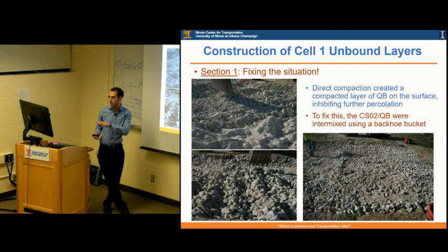Like a weak layer in between the two layers that is causing more permanent deformation, because permanent deformation is closely related to shear properties of unbound materials. So you don't have maybe the direct contact between the large rocks, which is giving the high shear strength of those materials when you have the quarry byproduct as a layer in between those two layers. So that might be an explanation, but later on when we do the trenching, we can know for sure what's going on.